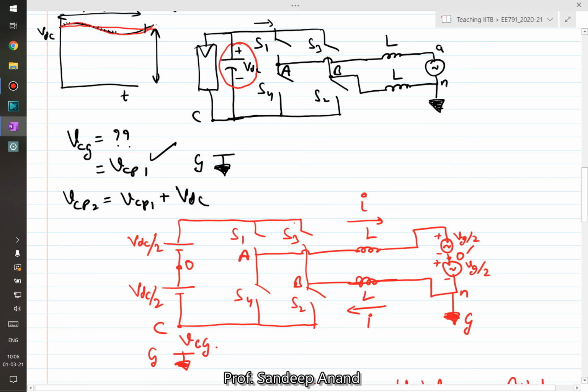That said, there are solutions, right? So even if you want to use, for example, unipolar modulation with the H-bridge, you can use it. There are some modifications in the circuit that one has to do, right? Which we'll see subsequently. It is possible. Obviously, there is a trade-off. You may, for example, have to add some additional transformer, which might increase the cost, which might increase the overall losses. But then yes, it will allow usage of even unipolar modulation schemes in the inverter, or you can do some circuit modification and then still achieve the benefits of unipolar modulation, at the same time avoid the leakage current.